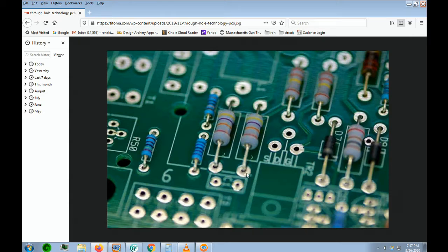The solder is going to adhere much better to the plating than it would to plain copper. The solder mask is just a little bigger than the pad itself, and it prevents any solder wicking from one pad to another or from a pad to a trace.